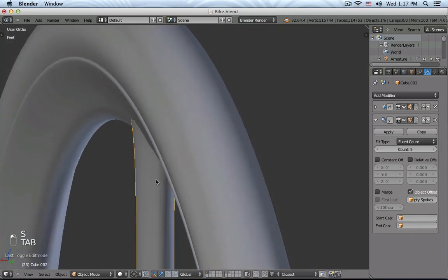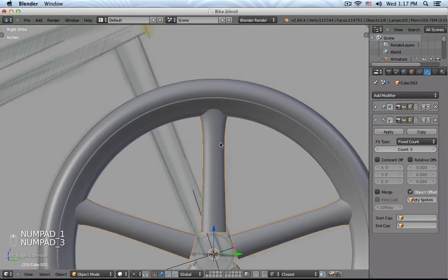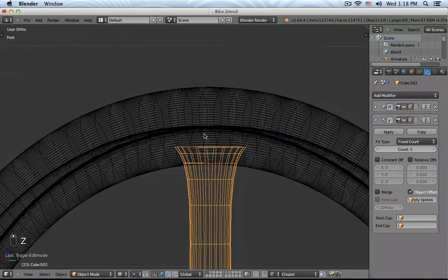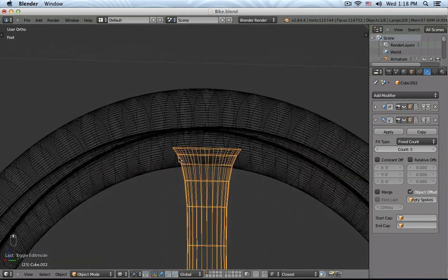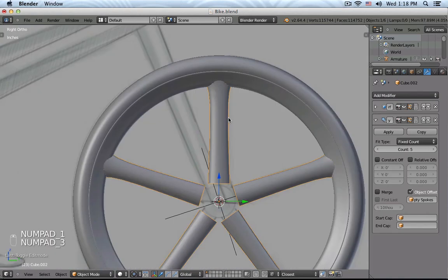when we bring this into Alias, Alias will get simply surfaces, and I predefined a little bit how they relate to each other. And then the blending, that is, for example, a fillet job, we then only do inside Alias. And to do this, of course, the surfaces have to intersect each other a little bit, so we can create the intersection curves and then trim it and finish it up.